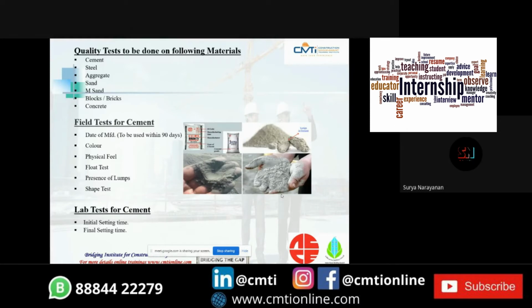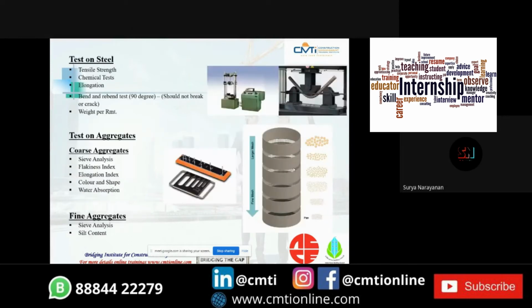The float test is when you take a pinch of cement and immerse it in a bucket of water, it should float for some time and then sink. If any lumps are present in a bag of cement, it should be discarded. And the shape test. Lab tests for cement cover initial setting time and final setting time, where we use the Vicat apparatus for testing the initial and final setting times of cement.